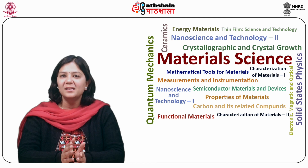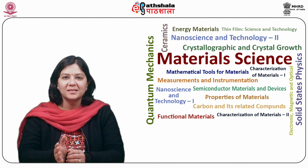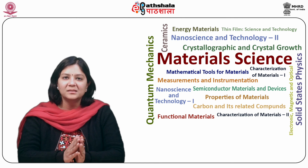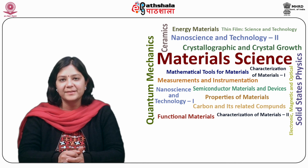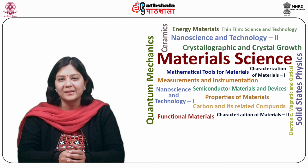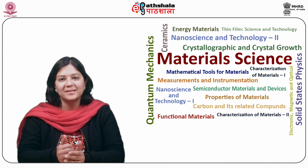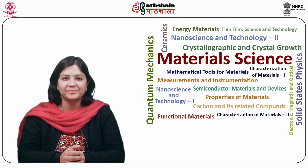Light sources. The earliest photolithography experiments employed UV light from mercury-based discharge lamps, which also used a combination of mercury with noble gases like xenon. Such lamps emit light with a broad spectrum with a significant peak in the UV range. This spectrum could be filtered to obtain individual spectral lines. Mercury lamps used in lithography exhibit spectral lines at different positions. These are 436 nanometers, 405 nanometers and 365 nanometers.